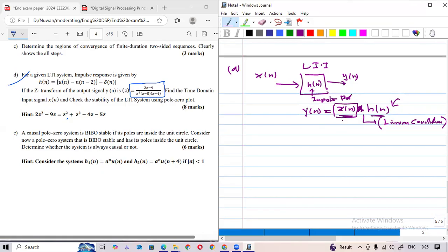So you can do the inverse convolution, so you have to use another method for that. I think you can understand what I'm saying. If you are given x[n] and h[n], you can perform the linear convolution, no issue. But you are not given x[n]; you are given y[n] and h[n], and asked to find x[n].